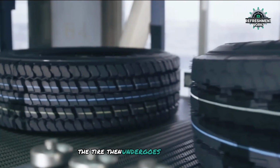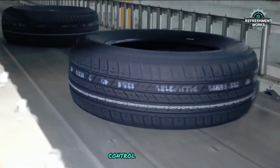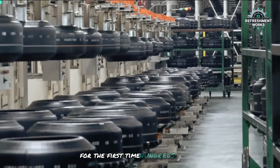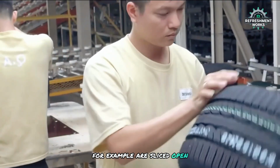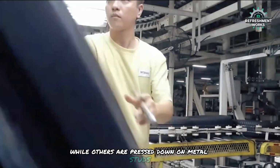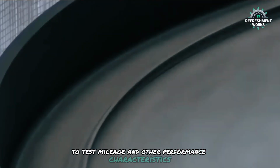The tire then undergoes a thorough inspection to detect any defects or abnormalities. This step is crucial to ensure quality control and safety. When a new tire design is being manufactured for the first time, hundreds of tires are taken from the end of the assembly line. For destructive testing, some of the tires, for example, are sliced open to check for air pockets between body plies, while others are pressed down on metal studs to determine puncture resistance. Still other tires are spun rapidly and forced down on metal drums to test mileage and other performance characteristics.